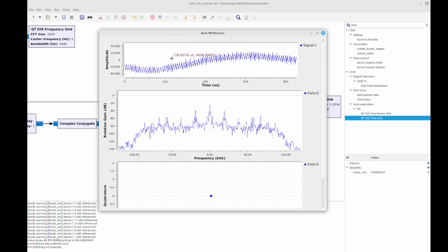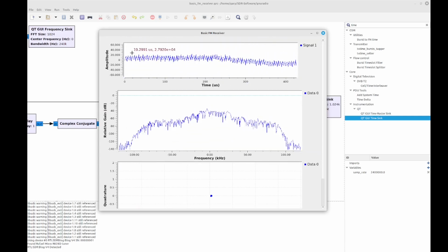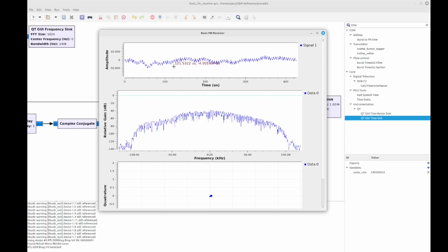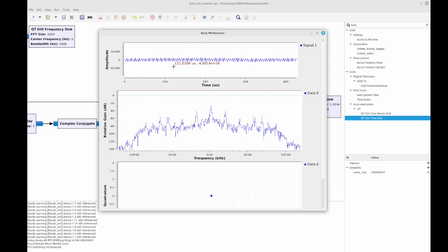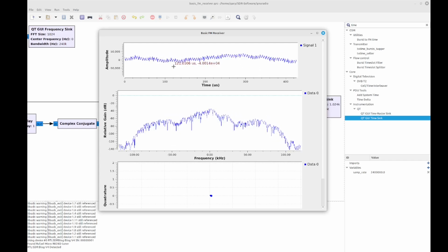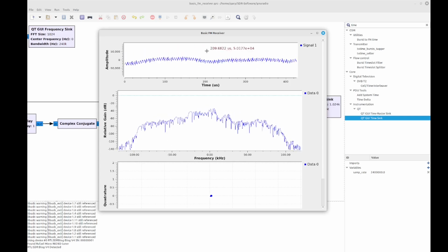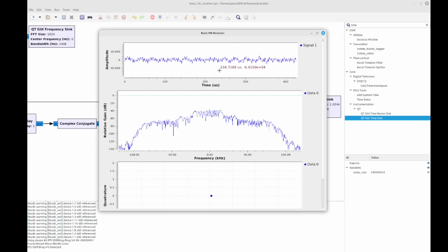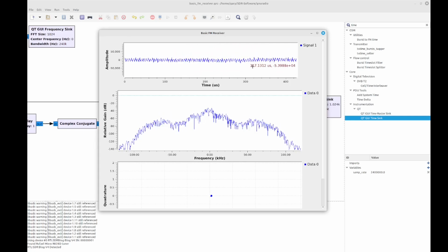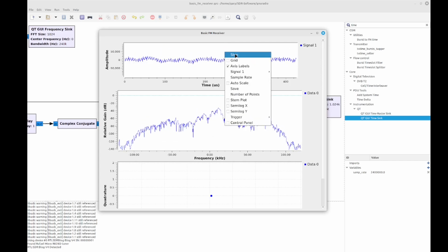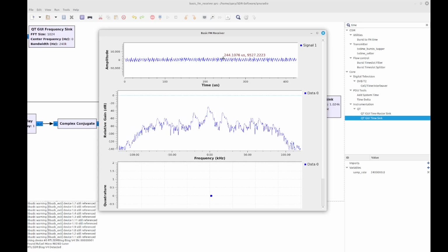And I've got values that are plus or minus almost 80 kilohertz. Well, if you remember, I said that the deviation of US FM broadcast stations can be anywhere from 75 up to 82.5 kilohertz. What you're looking at is the raw deviation of the carrier. This is actually in hertz. So if I wanted to, when it's at a peak volume, I could stop this and measure what the actual deviation is of the signal at any particular point in time.